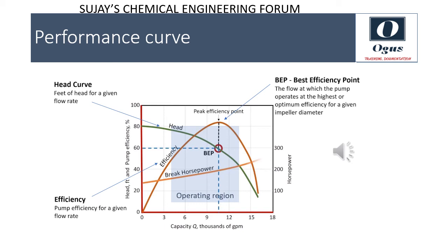In the same manner, the pump head drops suddenly after certain high flow point, which is the end of the performance curve. The pump must never be operated beyond the curve. Trying to run a pump off the right end of the curve will result in pump cavitation and eventually destroy the pump. The suction and discharge pressures fluctuate wildly, pulling and pushing the impeller about because of the out-of-balance forces. The shaft rattles, mechanical seals are damaged, packing is worn, bearings are destroyed and shafts are bent. Pumps will be noisy, vibrate and shake, get hot, and the microjets of liquid ejected by imploding bubbles will hit and erode the impeller metal.